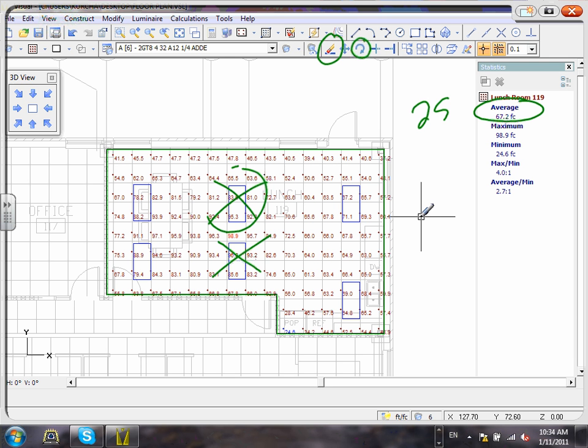Okay, I want to bring your attention to a couple of things, please, Jim and Camille, my friend. First of all, this is the number that you're going to be comparing with. But as you compare this number, Spencer, I want you to look at the minimum and the maximum: max to mini, and average to mini. This is another very important one. My average to mini is 3 to 1. 3 to 1 is actually great distribution, not too bad, except my averages are huge.